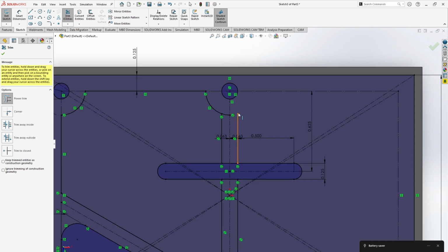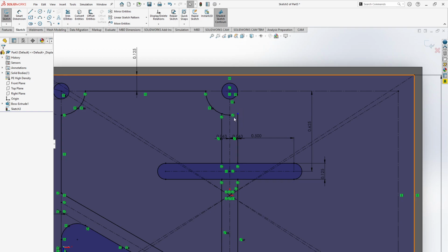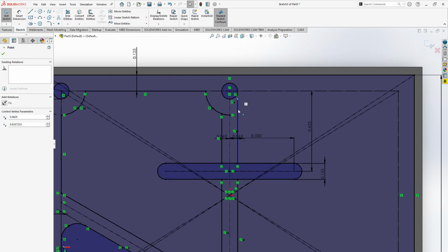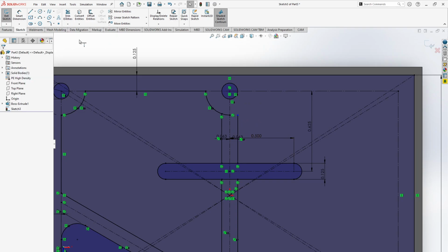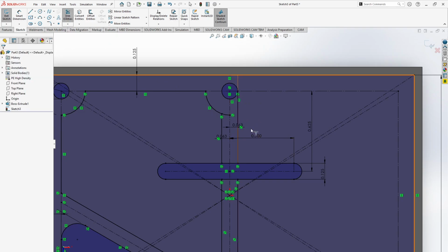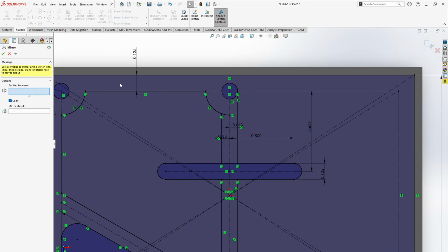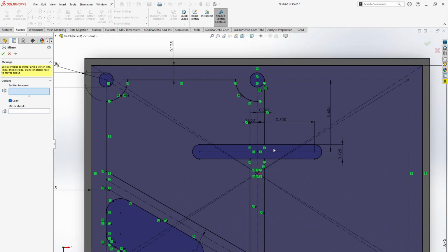Oh, interesting. Okay, since I cut off this line, this is the issue with trim entity sometimes. So now this is a blue line, now that I can move this around. What I'm gonna do is go here and click extend entities, and extend that all the way there. Cool. And again, I'm gonna do the same thing, mirror entities, and select all the things I want to mirror.